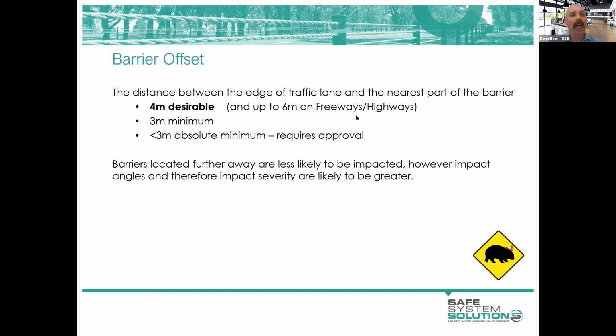And often you can utilise different roadside features, such as access points or other features that are in there, to give you areas where you can provide these breaks. Yes, because I know barrier offset is a controversial thing. Obviously, the closer you have it to the edge line, the more barrier across the state that will be rolled out, because it's cheaper to do that.